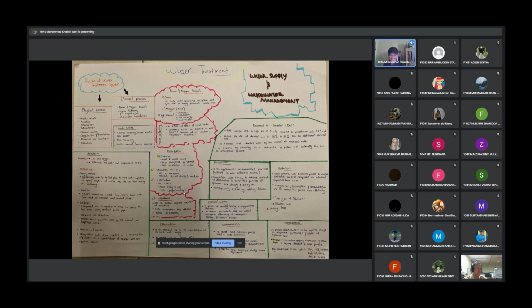And it also consists the water intake. The first one is coarse screening, trash rack or bow screen, and then fine screening, and after that grit removal or micro strainer.